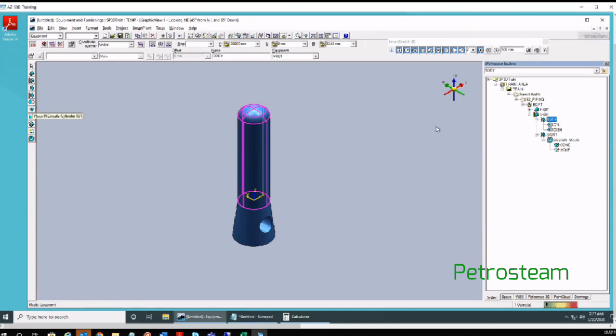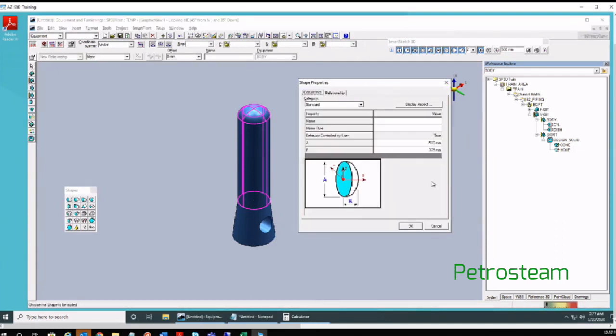So you missed the dish too. Now you select the body again and then come back to shapes. Once you activate it, select this dish shape. Again, for the dish, it remembers the values you have given earlier. I need the same values. Click OK.